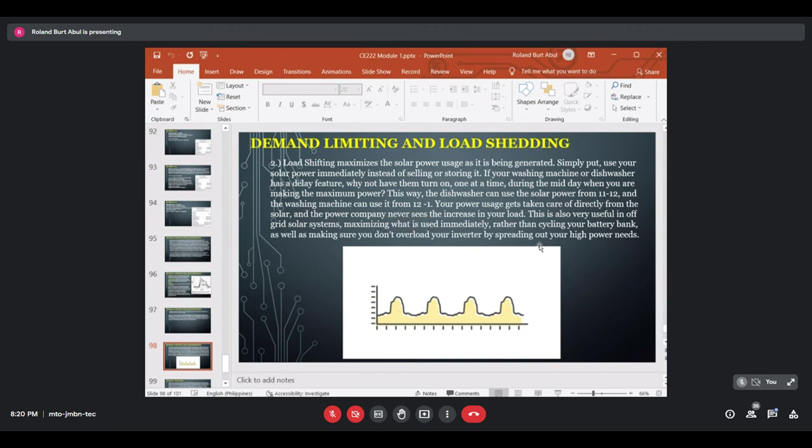In small installations, load shedding and shifting may be accomplished manually by scheduling the startup and shutdown of a piece of equipment during certain periods of the day when known peaks occur. In sophisticated commercial and industrial installations, load shedding and shifting may be accomplished with an energy management system that monitors demand and sheds and shifts loads in a prioritized manner.